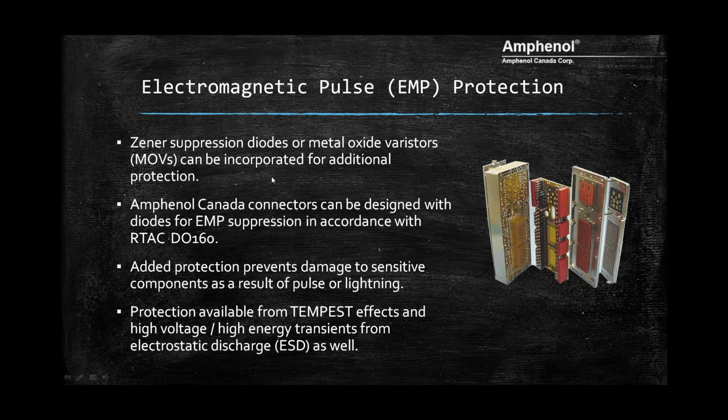So what this can do is, in case of lightning strikes or any spikes in any type of voltages and current, you can protect your box right at the entry level, rather than having the surge come in, possibly burning out the wires before it even gets to the circuit board. You can have everything filtered out and suppressed right at the entry level to your system.